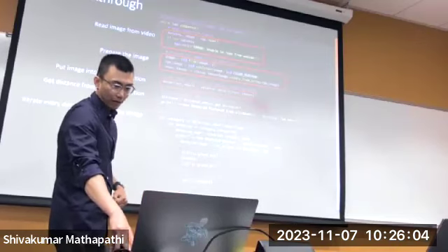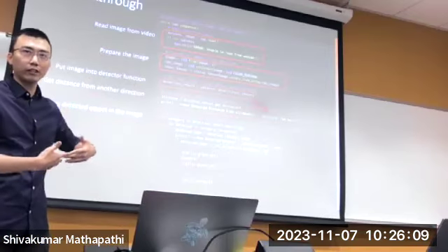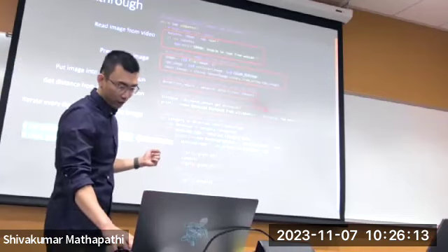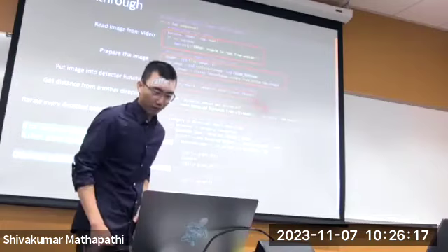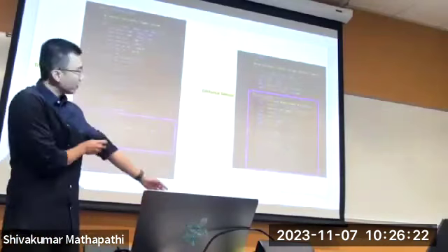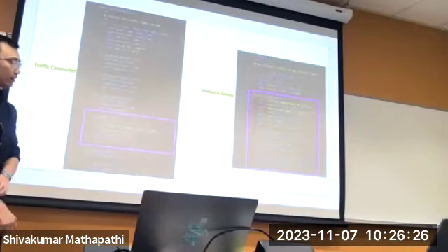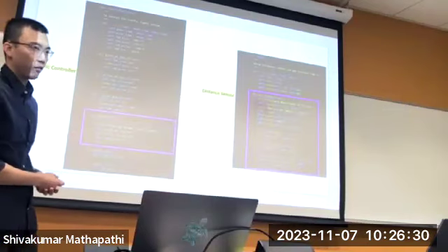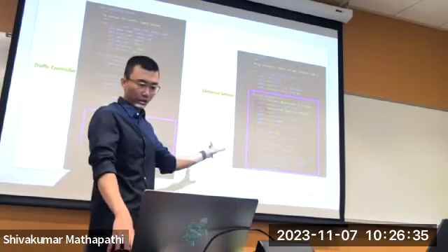In these two for loops, we look through every detected object to see if there's a car-like object. If so, turn on the green light for 5 seconds. If not, just run the normal traffic light. It doesn't hurt, right? Here is the traffic light controller that I use to control the LED lights. I put it into a class, so it's more modular and convenient to use. And that one is the ultrasonic sensor code used to calculate the distance.